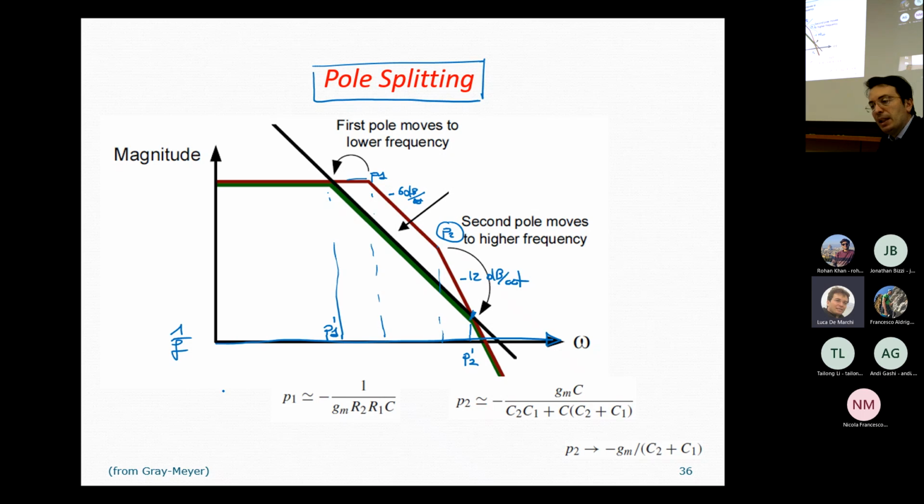And we have seen that losing phase can be complex, because what we are interested in is having a large phase margin, which means a phase curve much larger than minus 180 degrees. So the phase loss induced by the zero could become a quite relevant problem.